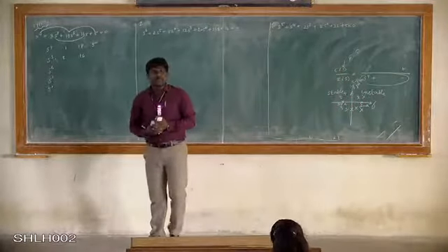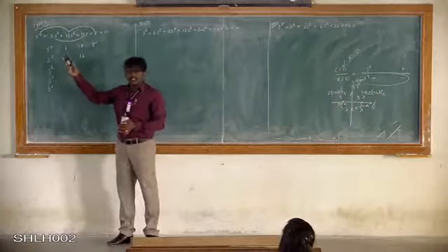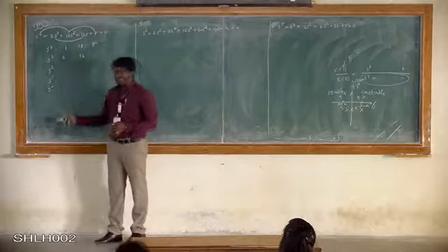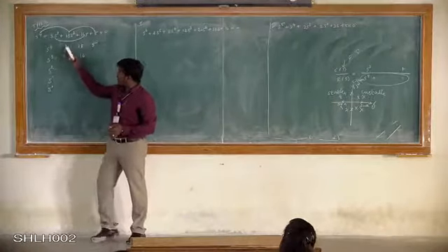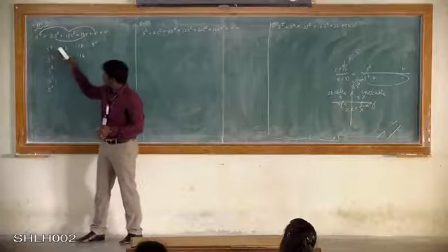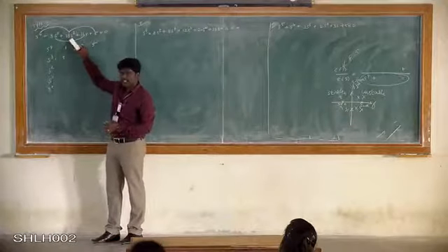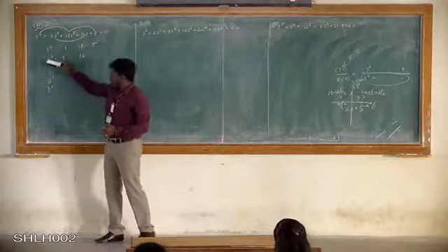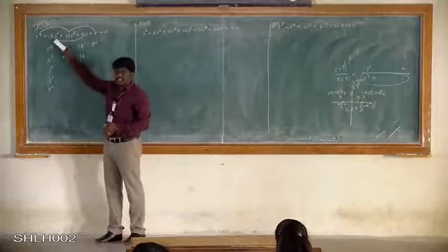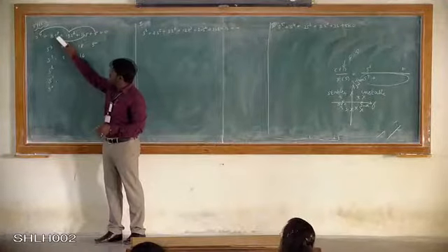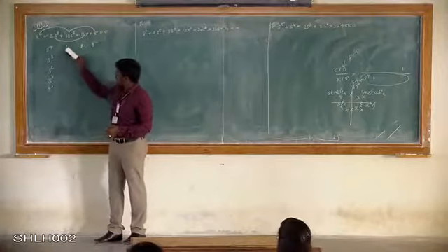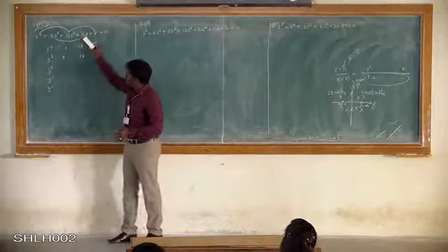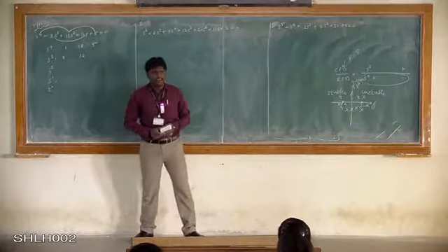First step is that, since it is a fourth order system, write S power 4 like that. Then write the coefficient near S power 4, that is 1, the coefficient near S squared, 18, then finally the constant value. For the next row, we start with S cube. The coefficient of that is 8, and the coefficient of S is 16, right?